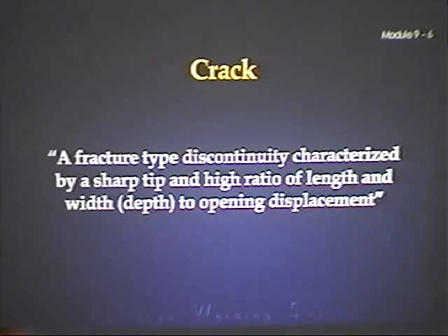The martensite forms while the metal is cooling at some temperature below 700 degrees Fahrenheit, and metal that has formed into martensite expands. This expansion of the metal results in internal stresses that may cause small micro cracks to occur on or just below the surface. That's what we were seeing there, micro cracks. If the arc is struck in the area over which the bead is to be deposited, the metal that is stressed or possibly cracked is melted a short time later as the bead is deposited, which eliminates the problem.